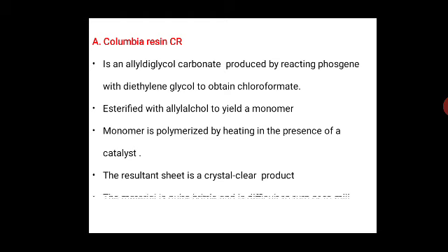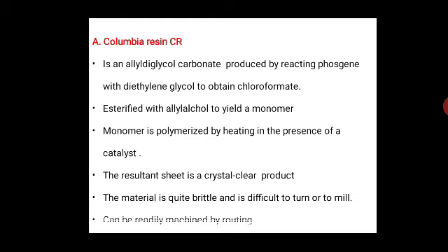This material has a relatively low fringe value, indicating low sensitivity, and its sensitivity index is very low compared to the others. It also has a low stress value at which it becomes non-linear. Therefore, CR39 exhibits appreciable creep, and the material fringe value must be determined as a function of time.